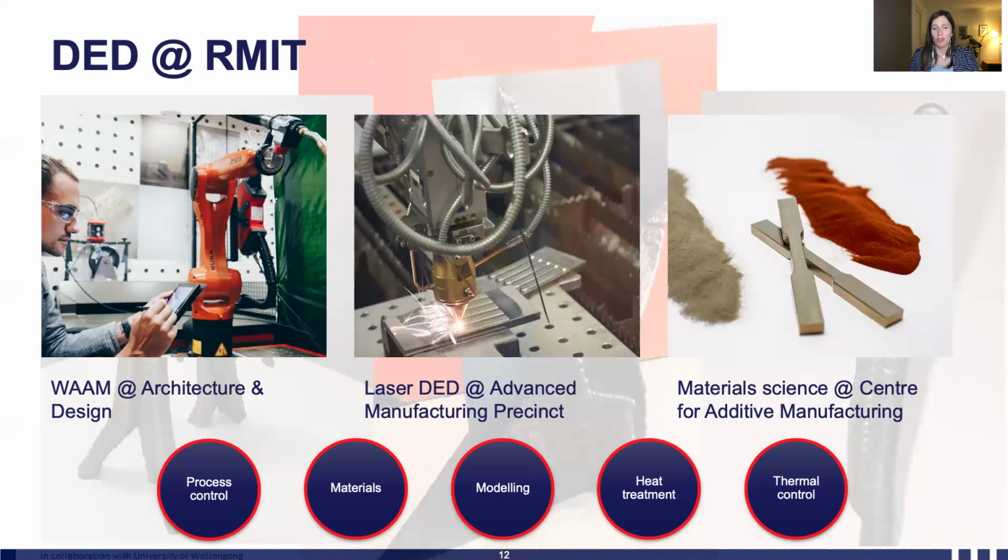And thermal controls, this is a really obvious one for WAAM, given the variance in the thermal history that we have in a part. We as engineers and scientists really need to do a better job of more accurately controlling the thermal history of a WAAM-made product so that you get better microstructure, better properties, and better performance, and can do that quite reliably and predictably.